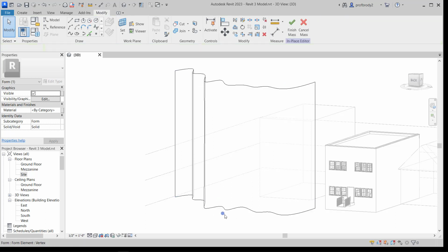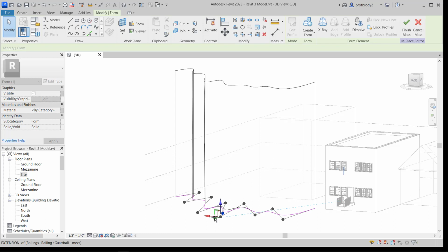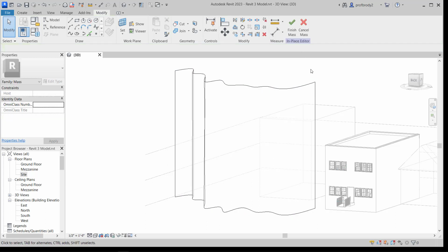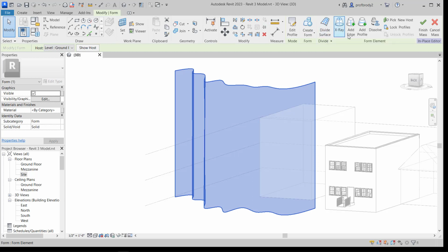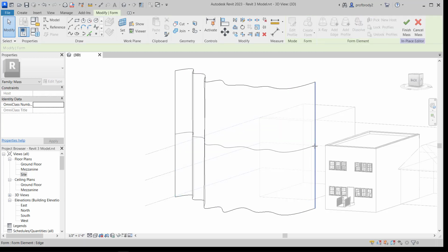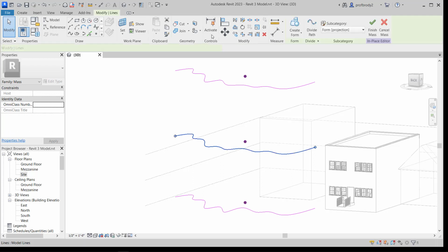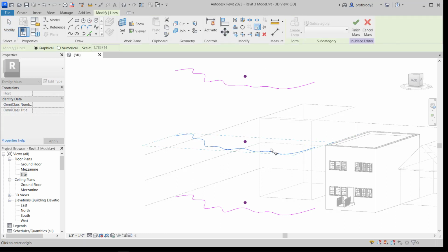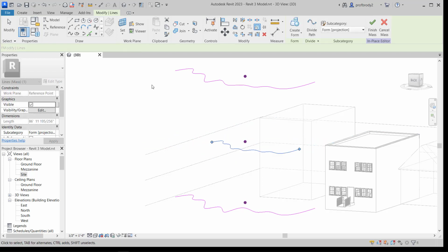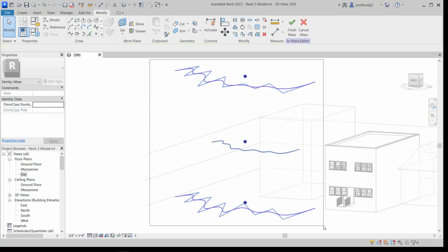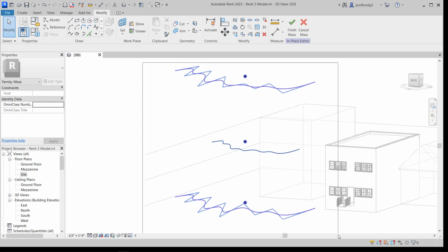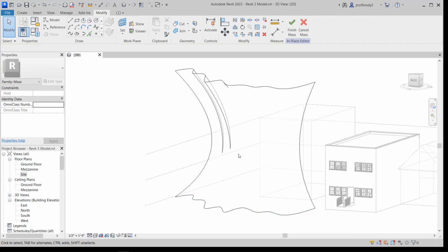At a smaller scale, this makes for a very nice curtain or thing like that. In fact, you can even gather the curtain, which is a fun thing to do, just by adding in, say, a profile in the middle, and then when you select the surface again, like we saw before, you can dissolve it. And maybe I'll just make this center piece a little bit smaller. I'll use the scale tool to shrink down the middle. There we go, a little smaller. And what you should see when you reform the surface is that it ends up being a gathered surface. Fun thing to do.